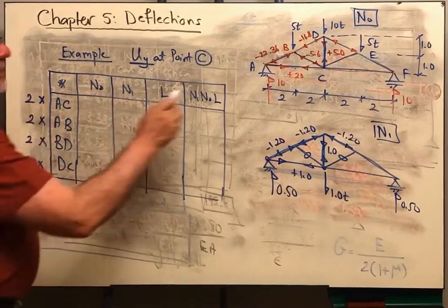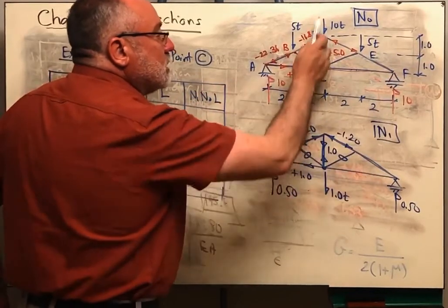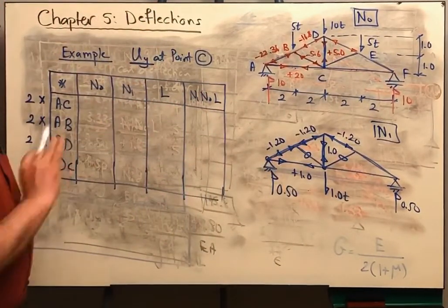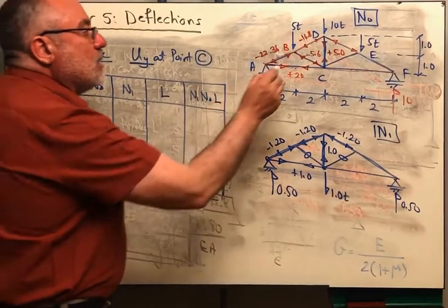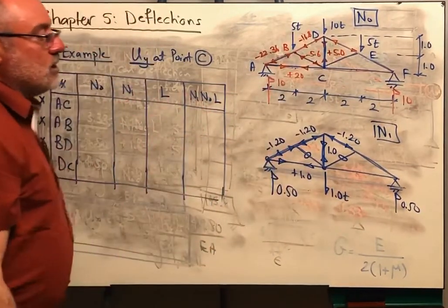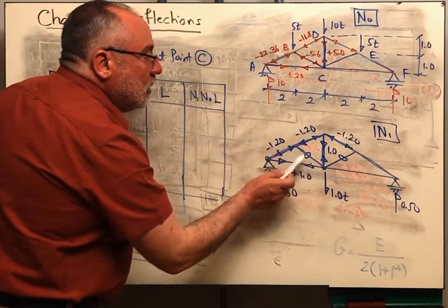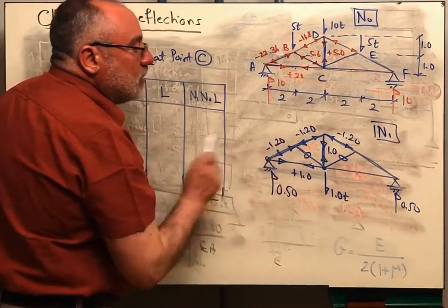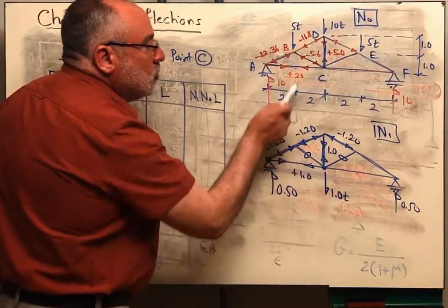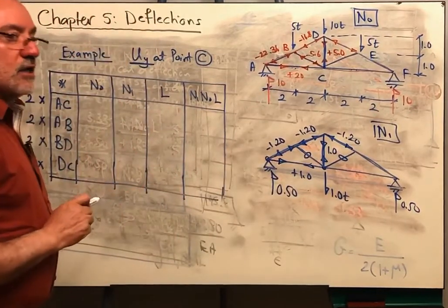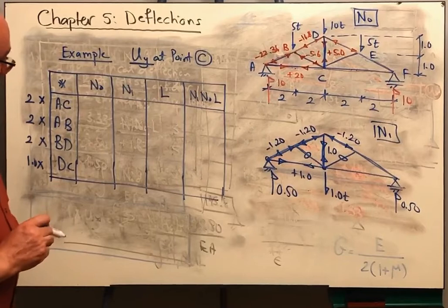So instead of writing all of the members of the truss, we just included half of them. And of course, if any member is not repeated, it will have to be included in the table. Also, if I'm having a zero member, I don't need to write it in the table because anyway, the 0 will be multiplied by this force and the result will be equal to 0.